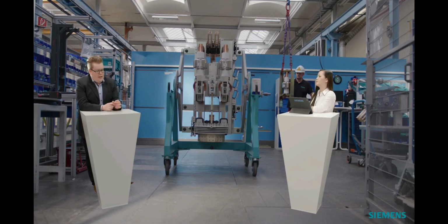Sure. What I've said is that the out-of-phase is only important for the fault synchronization. So the IEC/IEEE standard only requires a type test with an out-of-phase angle of 90 degrees. But there might be some cases where the out-of-phase angle can be up to 180 degrees. Very important for an out-of-phase calculation is to get the very detailed, full information about the whole system.